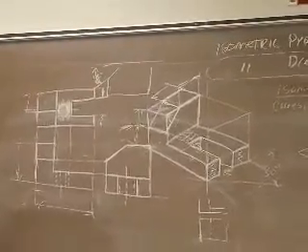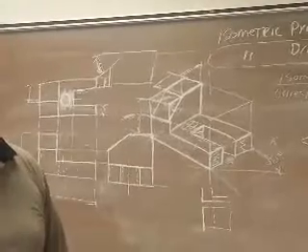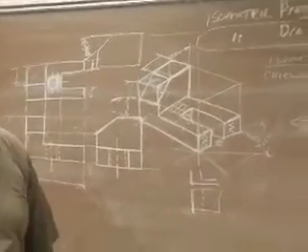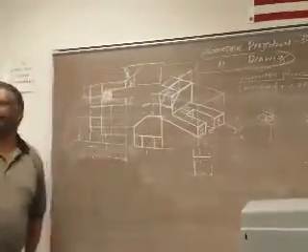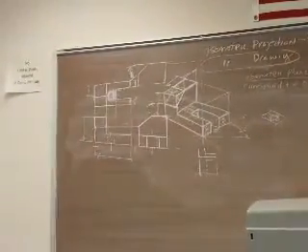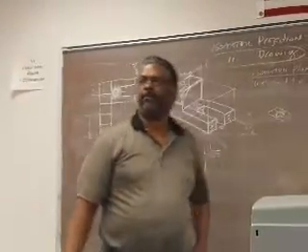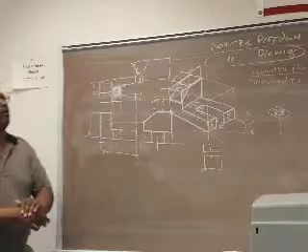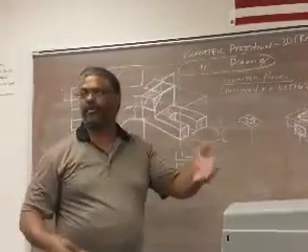I'm looking at the problem on 318. It shows a circle, and we could probably guess that's meant to be a hole in the object. How do you tell? It's understood to go through unless otherwise indicated. If there was a divot, it would be. In this case, it doesn't give you the diameters and so forth.